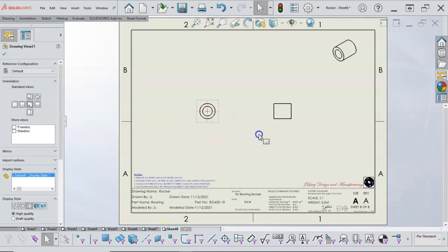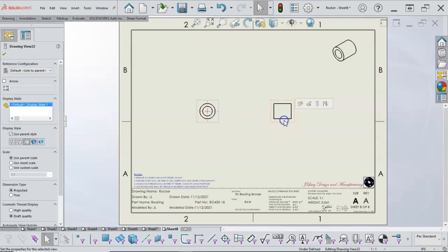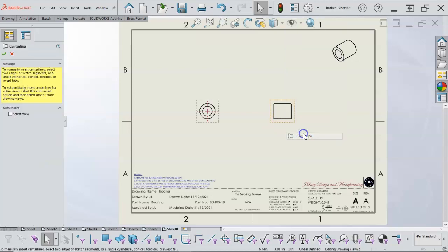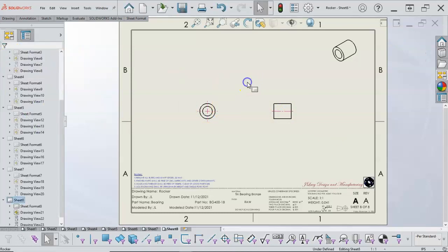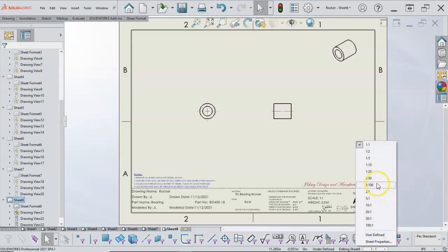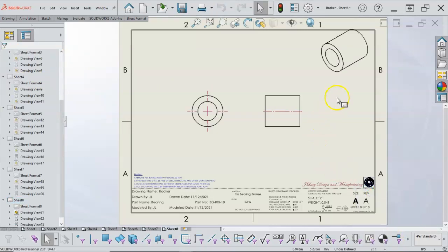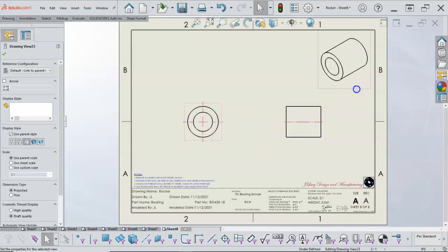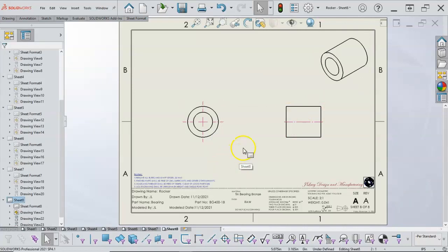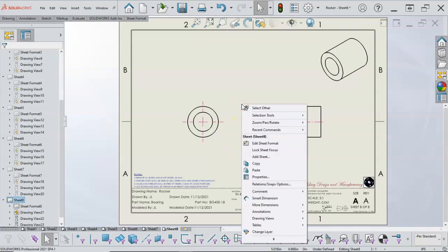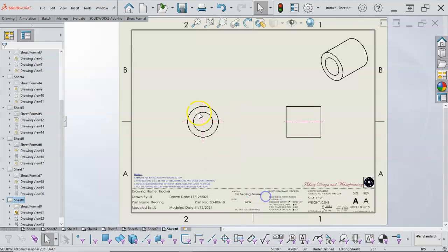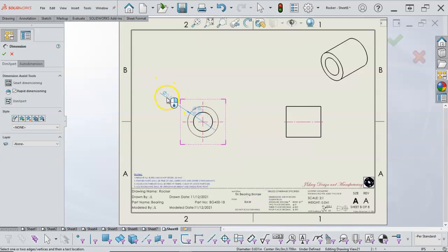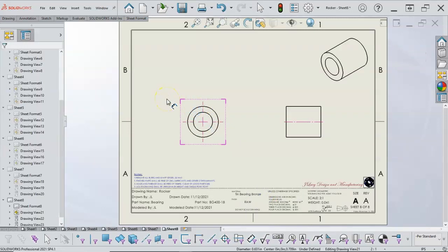And then the bushing. So if I wanted to do the center line, S key and center line, if I select the view, then it will go through the part. And those could go up a little bit in size. I don't want to get too crazy, but I'd like to fill the page up a little bit more. All right, and then just rough positioning for look. So since we're here, let's go ahead and put our smart dimension on the exterior. Oh, and we are in inch, pounds, and seconds, so that'll make it